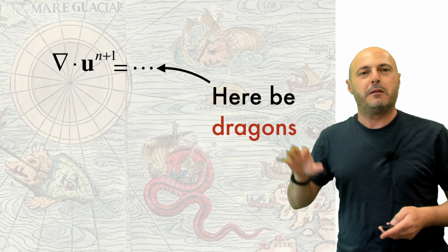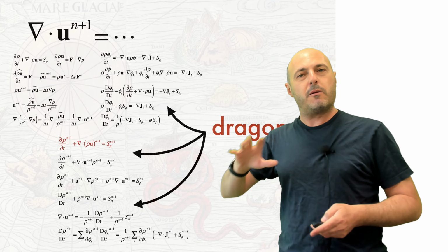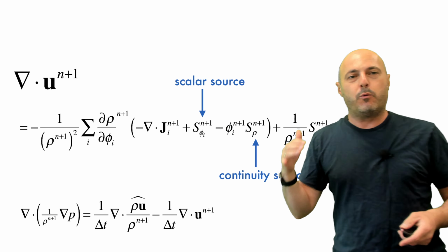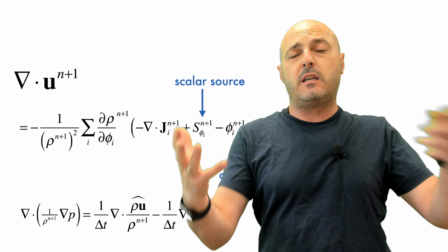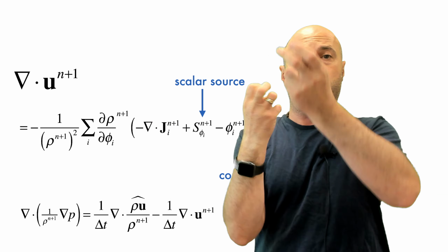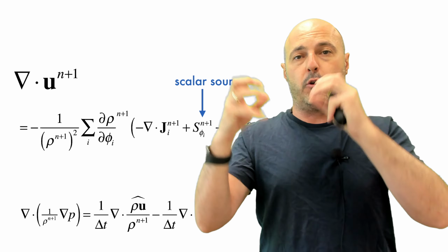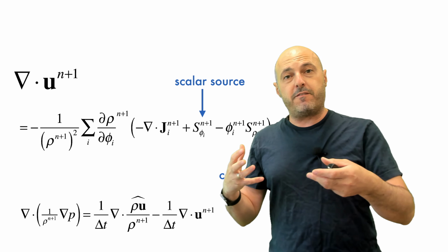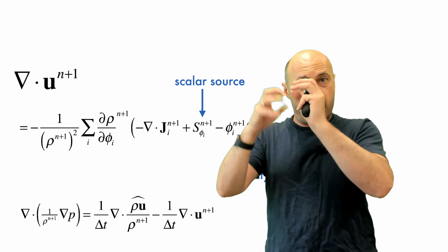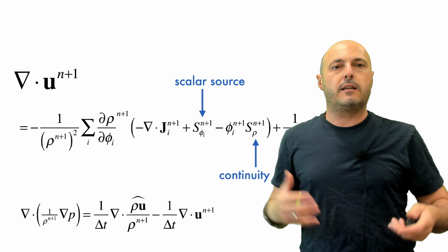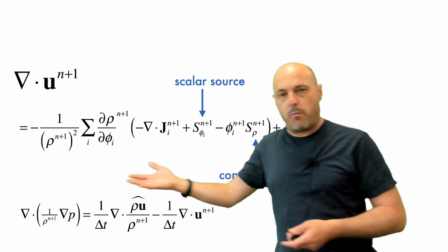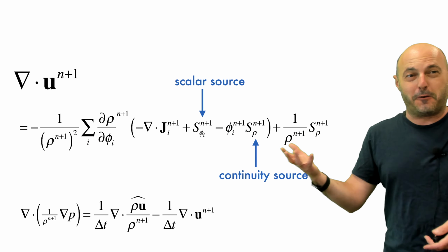Again, we have some papers about that, our algorithm that we have in our codes. So we do a bunch of things, we do all the math, and then we end up with a dilatation constraint for low Mach flows. Now, for constant density flows, incompressible flows, div u is 0. There's no dilatation. A fluid volume, a fluid element, has to remain the same. Whereas when you have reactions, then that volume is going to change, okay? Because there's reactions and there's heat release, etc. So this is our model for low Mach flows with dilatation.